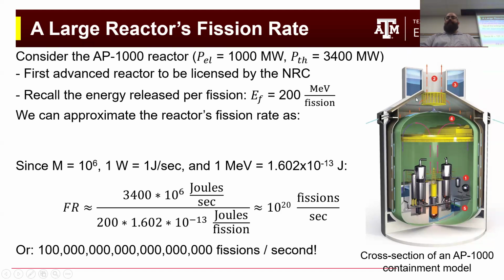And within this hat, there's multiple Olympic swimming pools worth of water that's just stored at the top so that if they have some kind of loss of power accident, they don't have to pump water in. They just open some valves that allows that water to dump onto the core or into the systems themselves so that you don't have to rely on pumps in emergency situations. And that's enough power to passively cool the reactor for a couple of days, which makes a lot of difference in terms of emergency response and getting backup power turned back on and stuff like that.